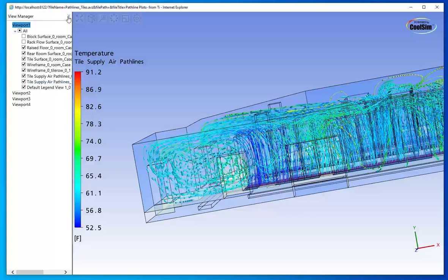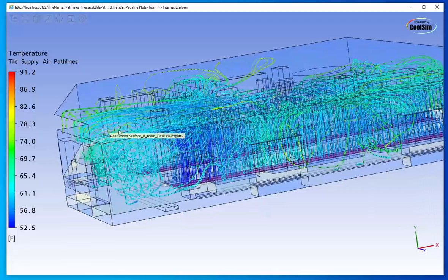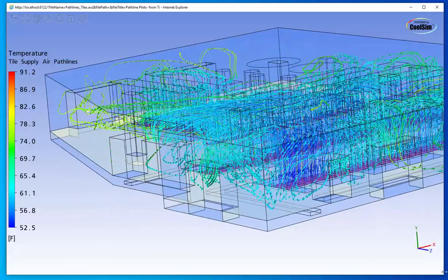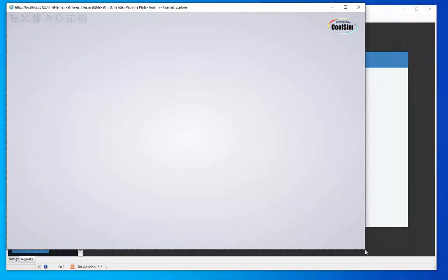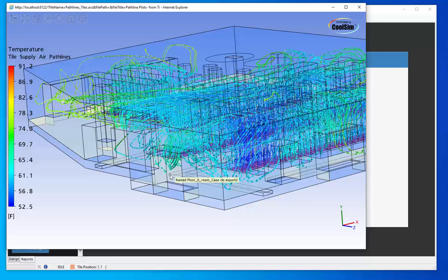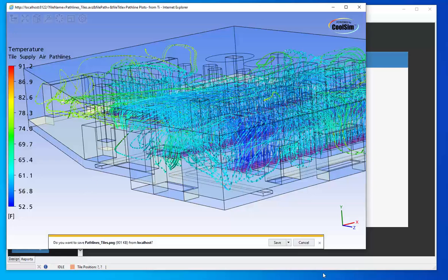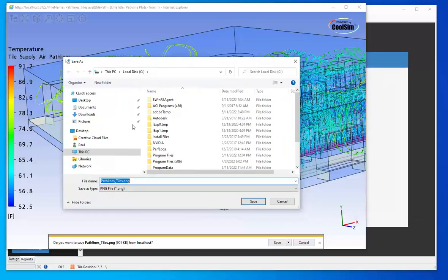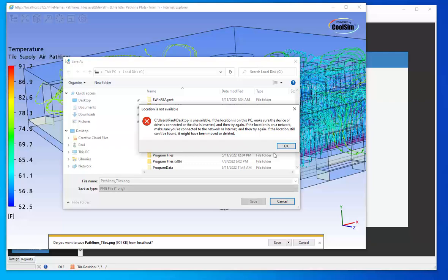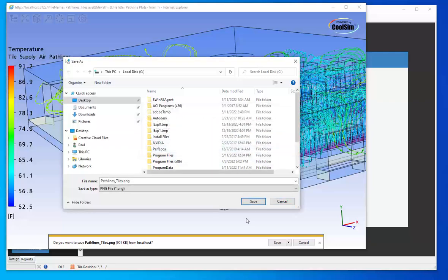If you wanted to make a shot of that again, if that particular image was interesting to you, you would set the size of this window to be whatever aspect ratio you want it to be. You can just stretch it to whatever you want. Select the P key for print, and it will ask you where you want to save it, and you can save it off using the file manager and put it in your directory anywhere you like. Just put it on my desktop and write it out as a PNG file, and that would be fine. So, yep.